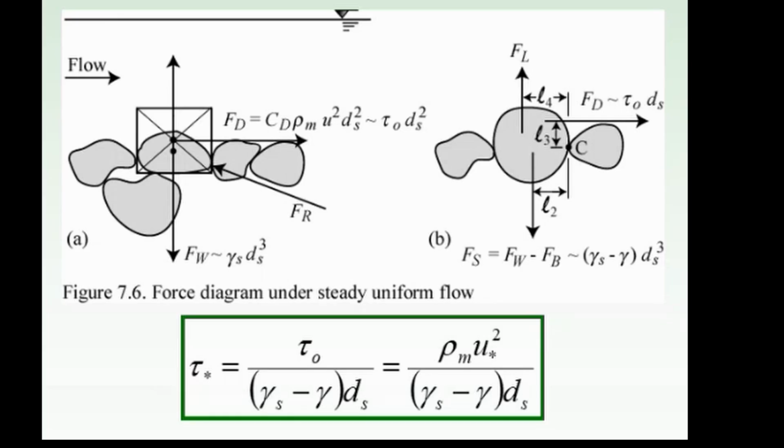There's a ds squared that cancels out here. That's the volume, that's an area. And we just take this thing here, and that's it, right? And we convert that shear stress into a shear velocity, which is by definition the square root of tau divided by rho, which is the square root of g H S. So then we have depth and slope, and then you have the shear velocity. That is a parameter that will come back today in my lecture as being one very important parameter for determining bed load, suspended load, and so forth.